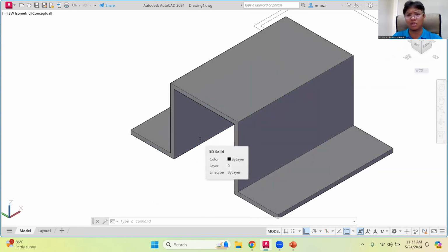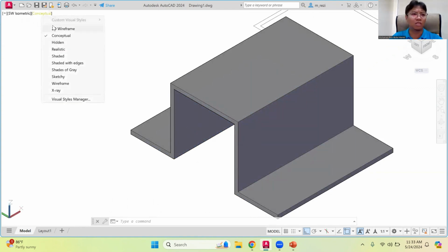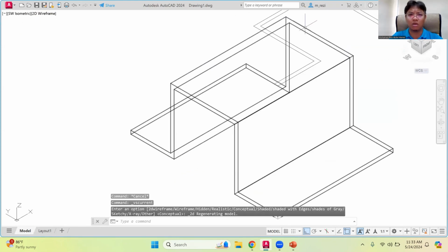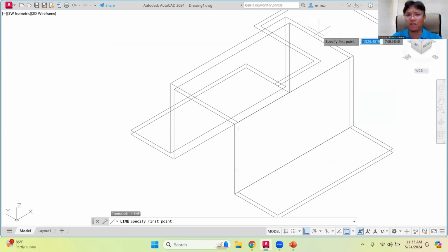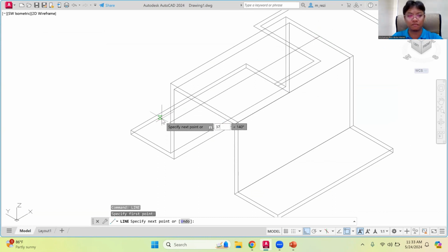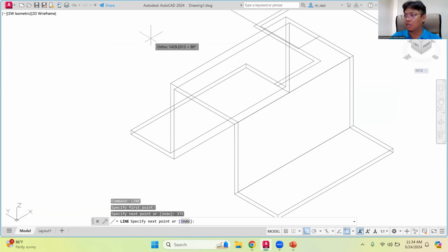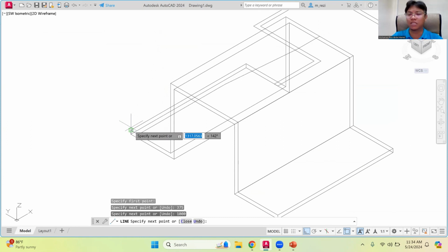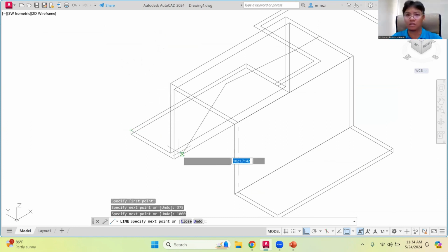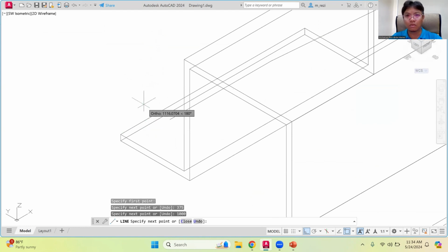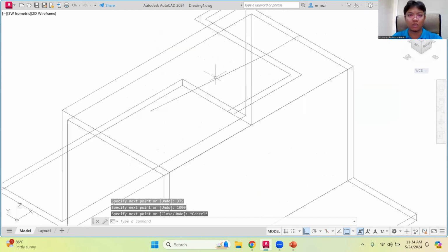Now there are many ways of doing this. So I think the simplest one is probably like this, switch to the wireframe. Now just type line. First you find the center of this object. So the first one is 375. The next one is 1000. Basically, these are the distances between all of the circles. Oops, why does it? No, I think that's just drawn incorrectly.